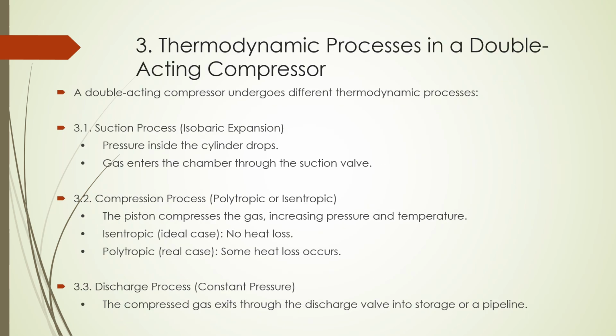Thermodynamic processes in a double acting compressor. Earlier we already explained what a double acting compressor is. A double acting compressor undergoes different thermodynamic processes. One, we have the suction process, which is isobaric expansion. Pressure inside the cylinder drops. Gas enters the chamber through the suction valve.